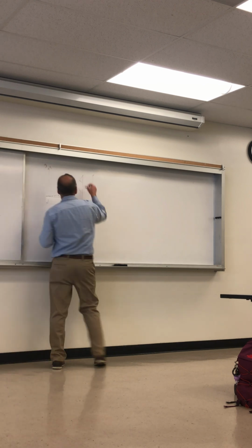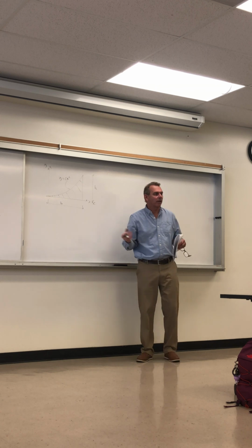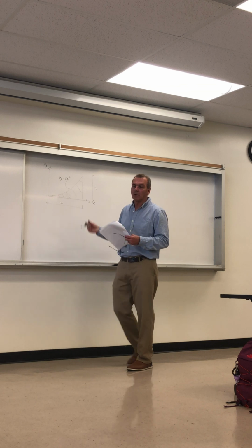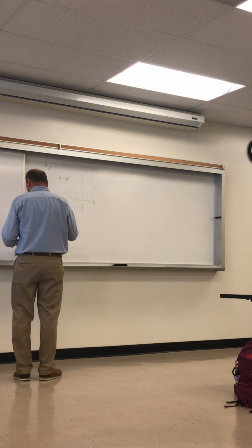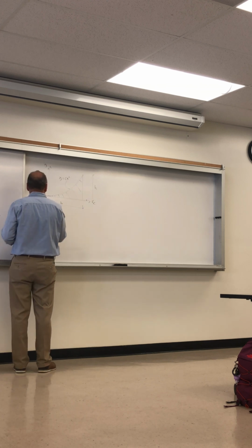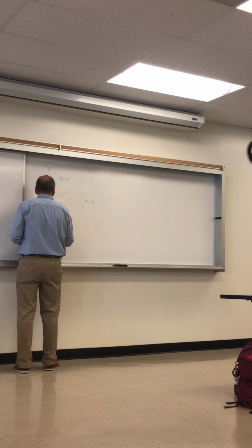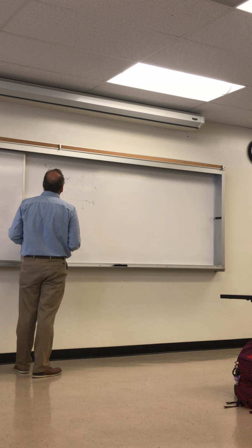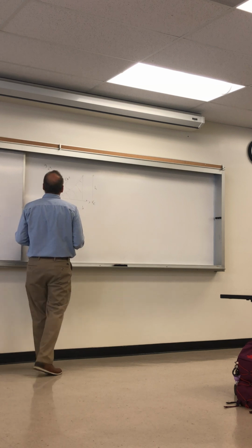The upper side is defined by that equation. So imagine a piece of wood cut with this, so you have this solid piece now, right? This area. And we can calculate the centroid, we've done that before, and now we want to calculate what the moment of inertia is about the x-axis. Ix is the integral over the area, y squared dA. So let's go up.